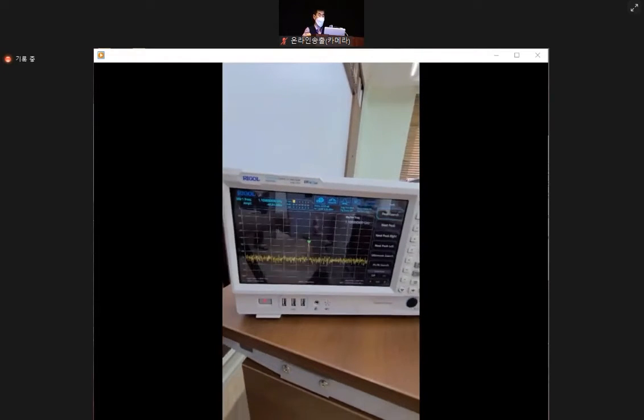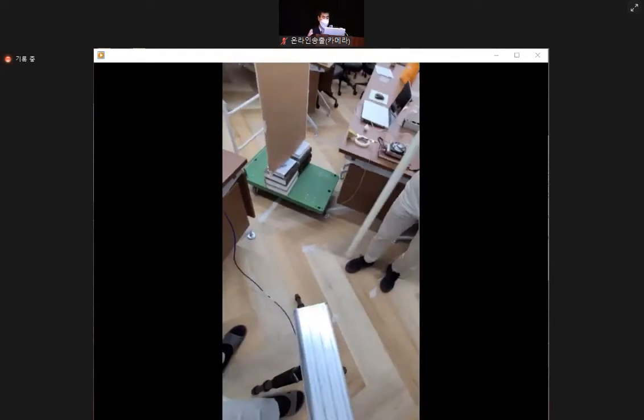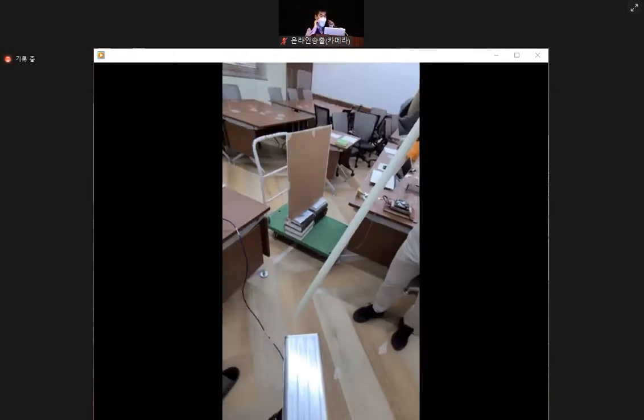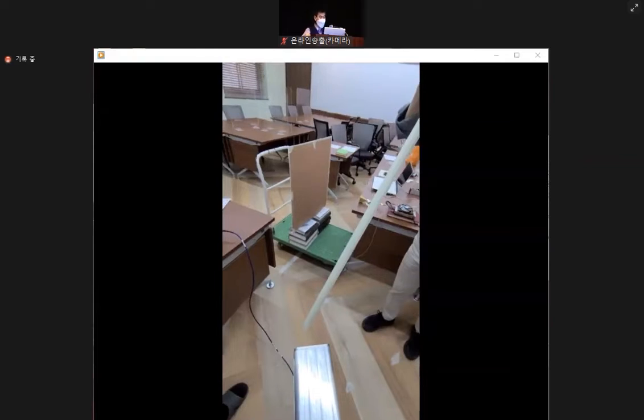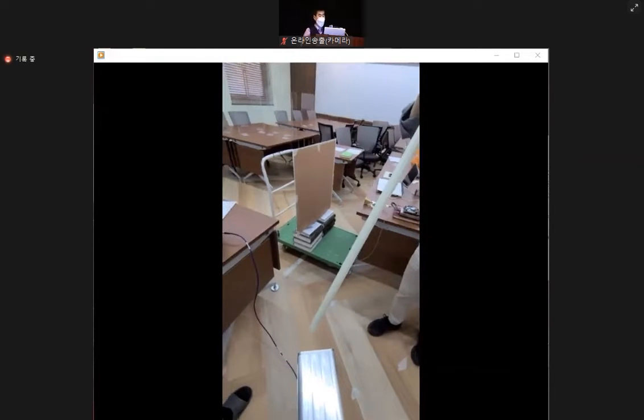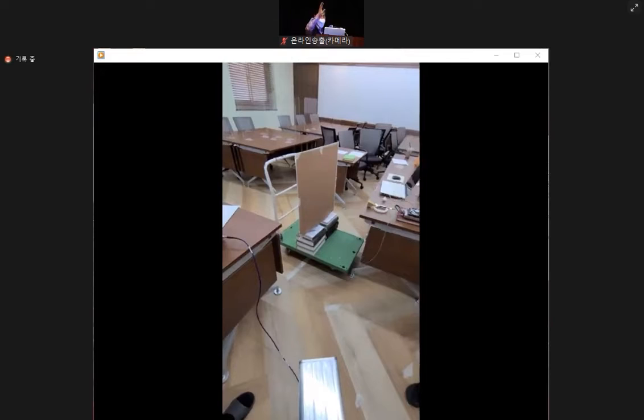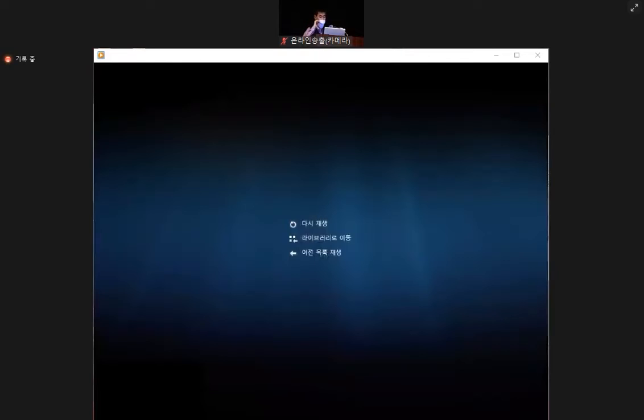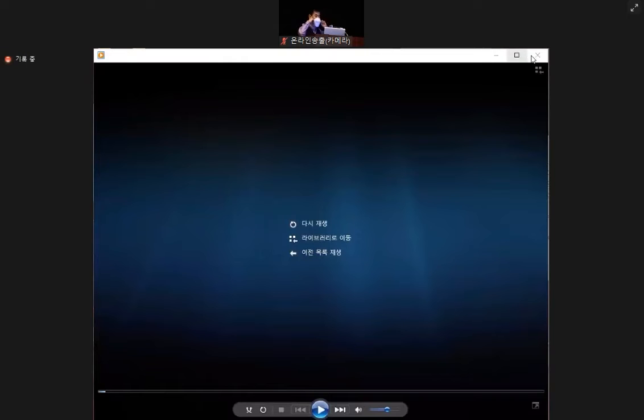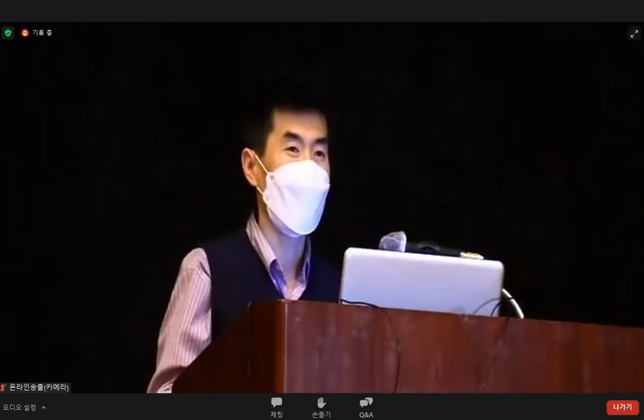By watching the animation on the spot, it's hard to read the tiny numbers of the signal strength. But the receiving power has gone down, definitely telling what we expected. At the 45 degrees of observation, that was the best and the highest in strength, around minus 40 something dBm. But at other angles, such as 20 degrees or 60 degrees, it will go down by 10 dB like that, or more than 10 dB.